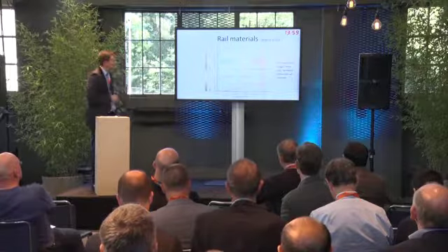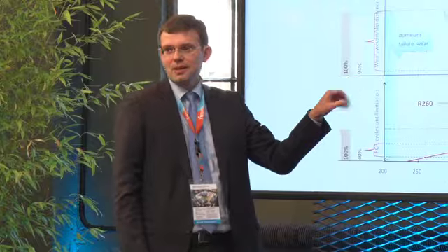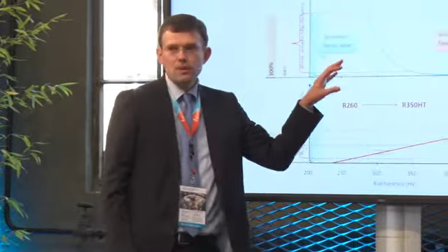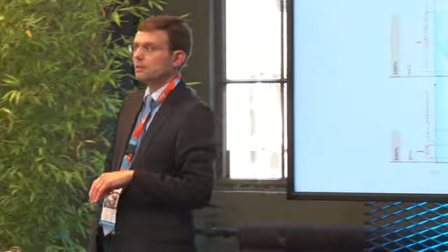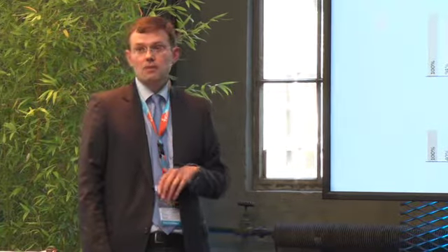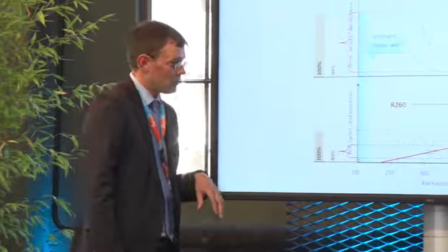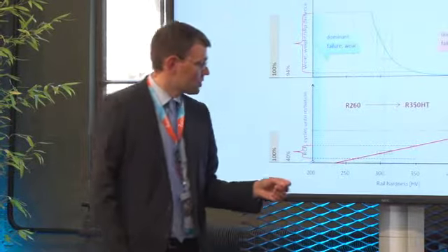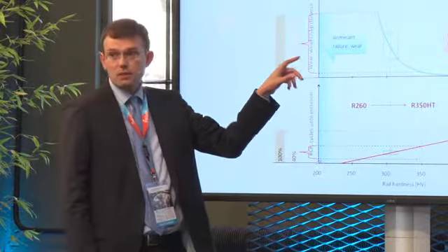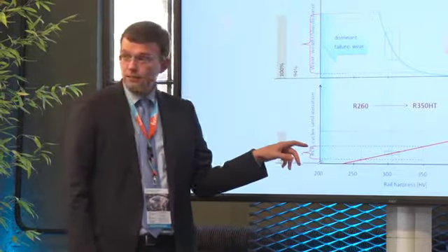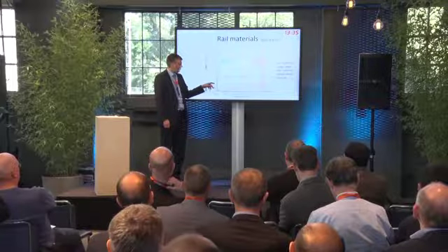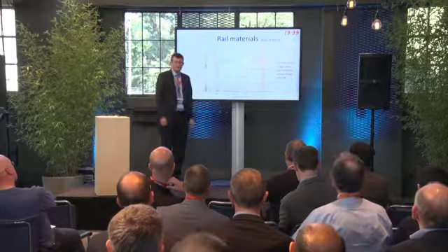materials. I think that for most of you, this picture looks quite cryptic, but I'm going to explain it. I think most of you are very familiar with the basis of this picture. I just took it from an InnoTrack report, and this InnoTrack report compared the behavior of different rail grades in terms of wear, sensitivity to wear, and RCF, so the number of cycles needed for a sample to initiate rolling contact fatigue.